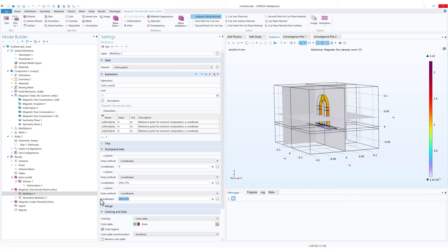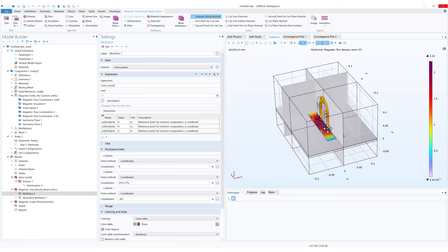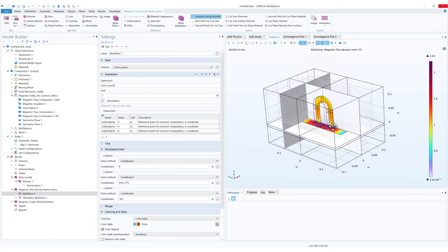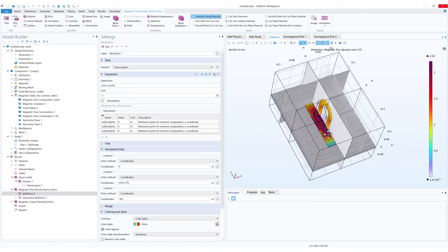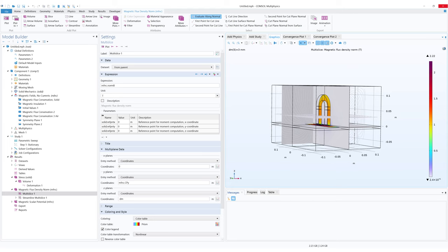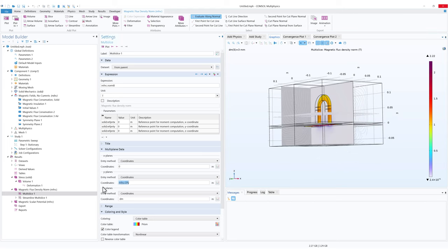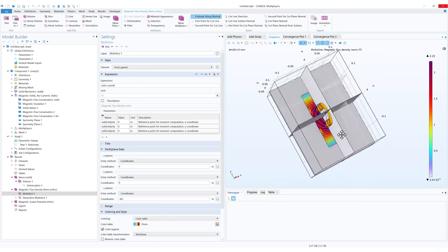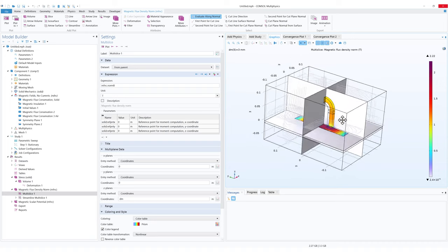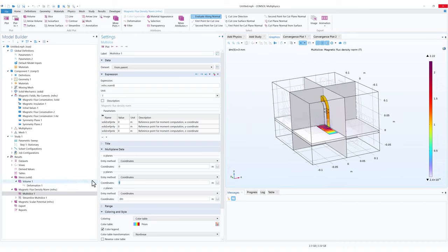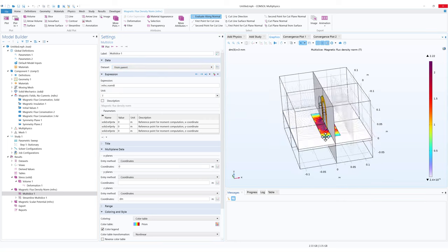For the Z plane we'll type minus dm and click on plot. Similarly the Y plane is fine, we can leave it as it is, or let us set the Y plane to 0 also. Now I hope the planes will be at the center cutting each other, or if we don't want, we can remove the Y plane so that we can have this structure.